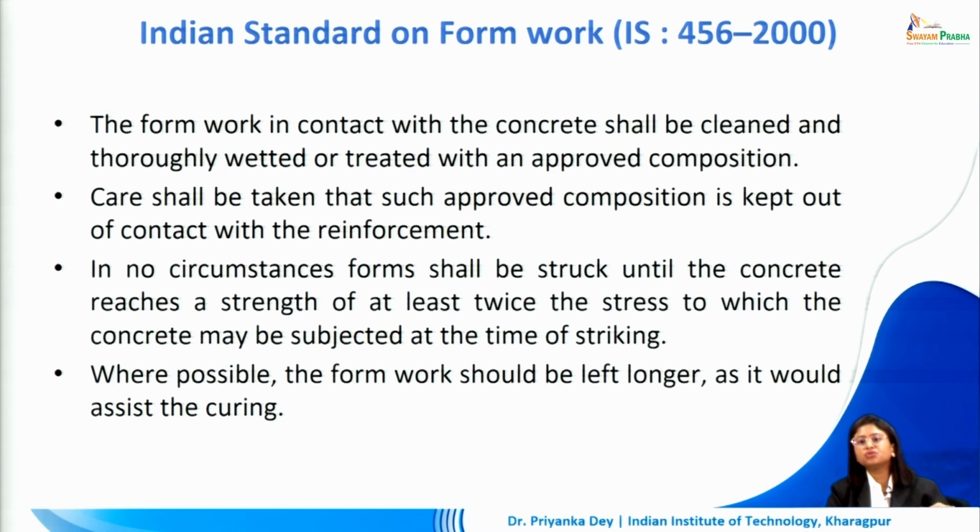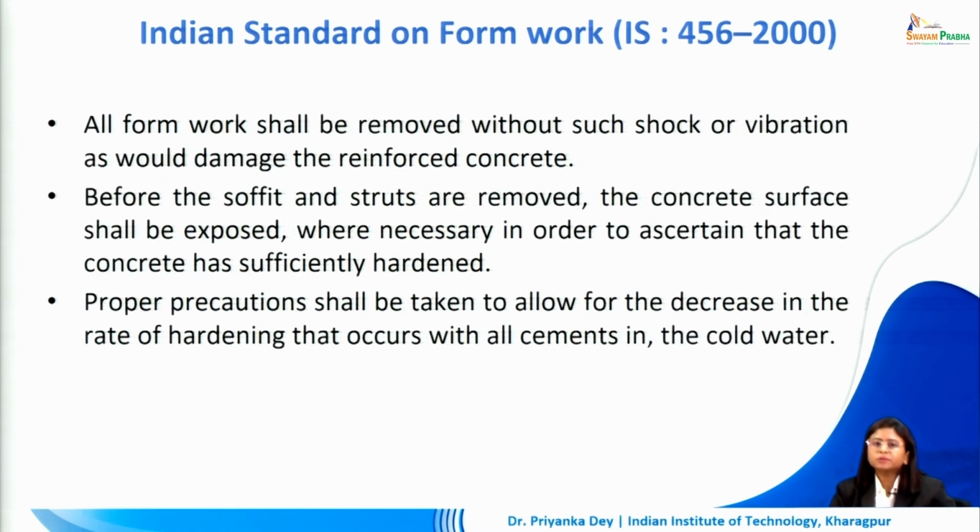It is best to let it rest for a significant amount of time while other construction works are being done, and one returns at a later date when the concrete has stabilized, has cured sufficiently, and then the formwork can be removed. The code also specifies that all formwork shall be removed without such shock or vibration as would damage the reinforced concrete. Before the soffit and struts are removed, the concrete surface shall be exposed where necessary in order to ascertain that the concrete has sufficiently hardened, and proper precautions have to be taken to allow for the decrease in the rate of hardening that occurs with all cements in cold water.